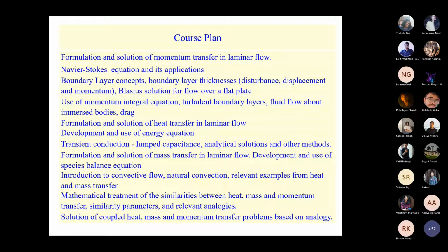Reynolds number, perfect. So Reynolds number is going to let me compare between situations where all these are going to be different. Everything is different, but the combination of velocity, density, viscosity, etc. is such that the Reynolds number is the same between two cases. Then we know that the flow pattern in these two systems is going to be similar. So that's why we call it a similarity parameter. It lets me compare between apparently dissimilar situations and arrive at conclusions equally applicable for both cases. There are other similarity parameters when you non-dimensionalize the Navier-Stokes equation, but the principal one is the Reynolds number.